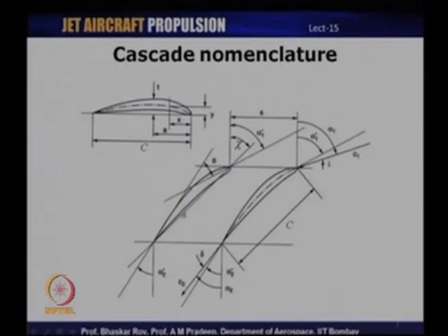Theta is the angle between the tangent to the trailing edge and the tangent to the camber line at the leading edge. This is the camber line, shown here by dashes and dots. If you draw a tangent at the trailing edge and a tangent at the leading edge, they meet and intersect at a certain angle.